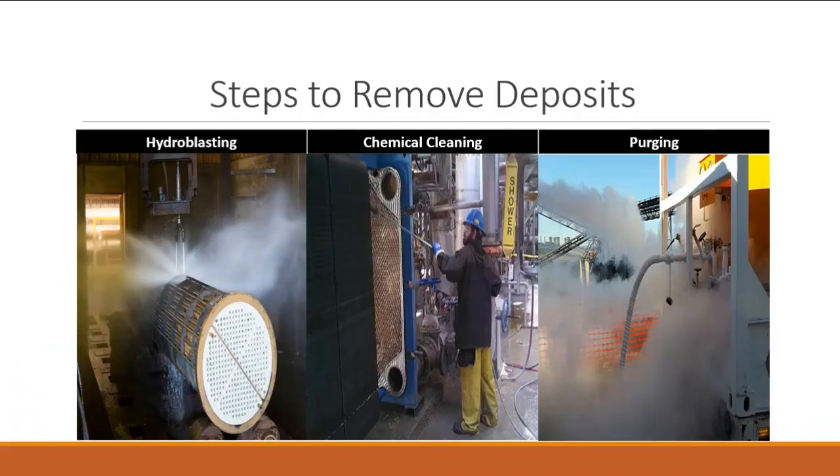The removal of deposits can be done by hydroblasting. If that fails, chemical cleaning is used to dissolve them. If the deposits still resist, the heat exchangers must be purged using noble gases such as hydrogen.